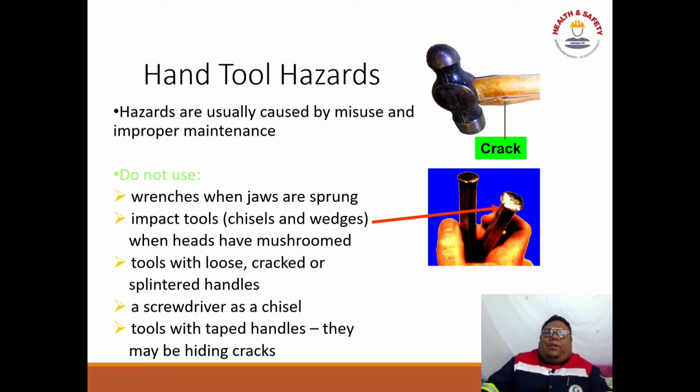This is a common issue, guys, on the construction site. You know what the cause of this is: if you hammer it, the hammer will slide off and go to your hand. If you have no gloves, it is the cause of an accident. That is a pinch point. When heads have mushroomed, this is what we call mushroom heads. Also avoid tools with loose, cracked, or splintered handles, and a screwdriver used as a chisel.